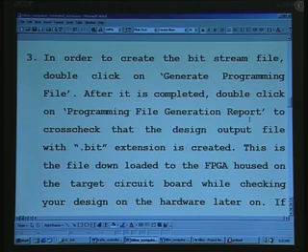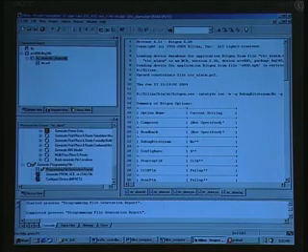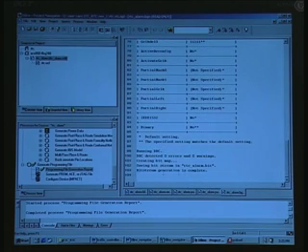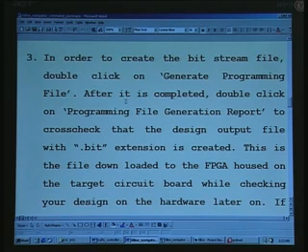This is precisely what we have done, to cross check that the design output file with .bit extension is created, and that is over earlier. So a tick mark is got, and in this file if you see towards the end, I will just read out. It may be difficult for you to read yourself. So what it says is saving bitstream in RTC_alarm.bit. So this implies that bitstream generation is complete. That is what it reports towards the end. And coming back to this command summary, we were here.